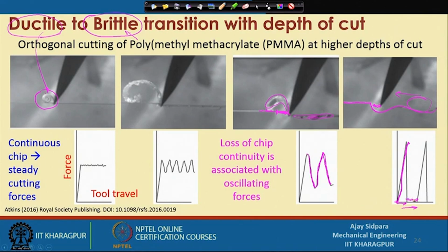This is the non-contact region. Your tool has removed this much material, scooped it out, and then the tool comes into contact again. After the off time, you will again get the same peak and the same fashion of the first trend, and again you get this removal.